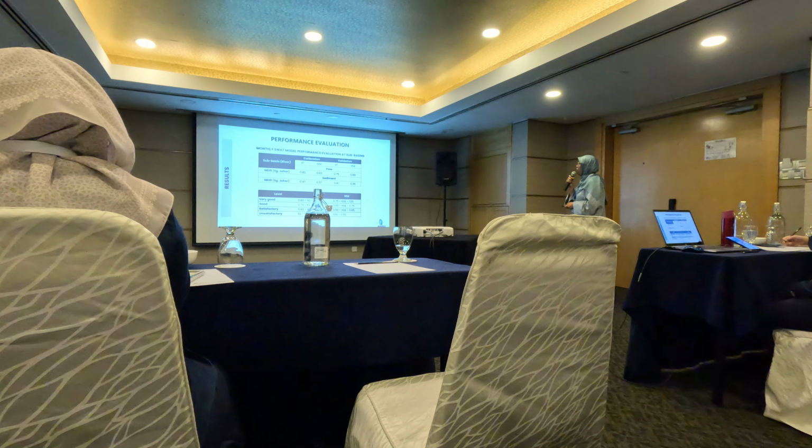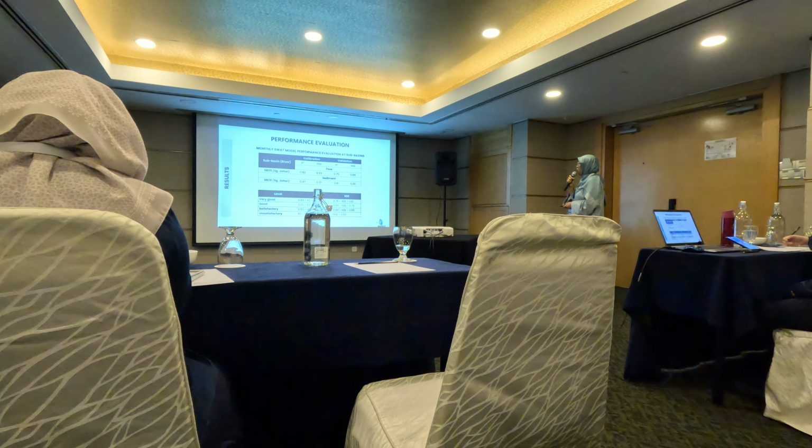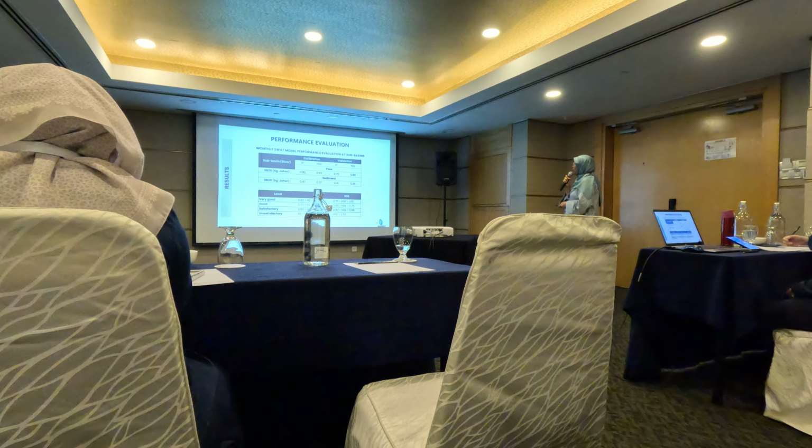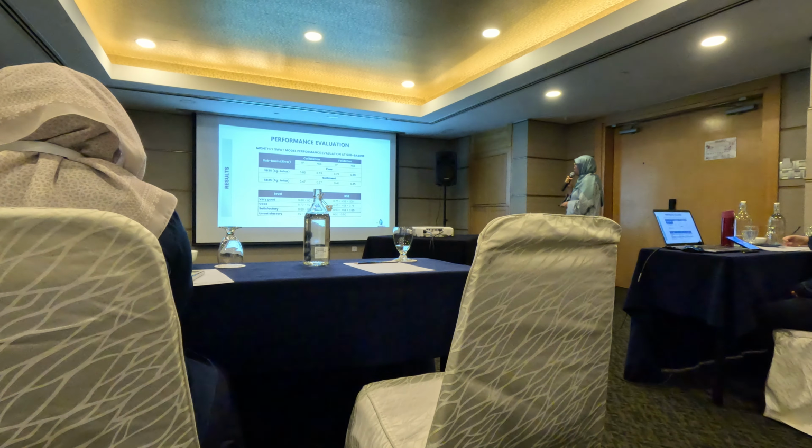So this is the overall performance evaluation for the monthly SWAT model performance at sub-basin 35, Sungai Johor. Based on this performance, for flow, R square is very good, and NSE is good only.